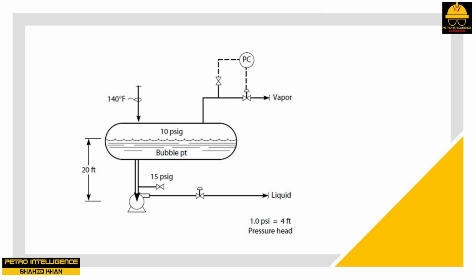As the pump's discharge valve is opened, the velocity in the suction line increases, reducing the pressure at the suction of the pump. The faster the discharge valve is opened, the greater the acceleration in the suction line, and the greater the loss in the pump's suction pressure. If the pressure at the suction of the pump falls to its bubble or boiling point, the liquid will start to vaporize. This is called cavitation. A cavitating pump will have an erratically low discharge pressure and an erratically low flow.